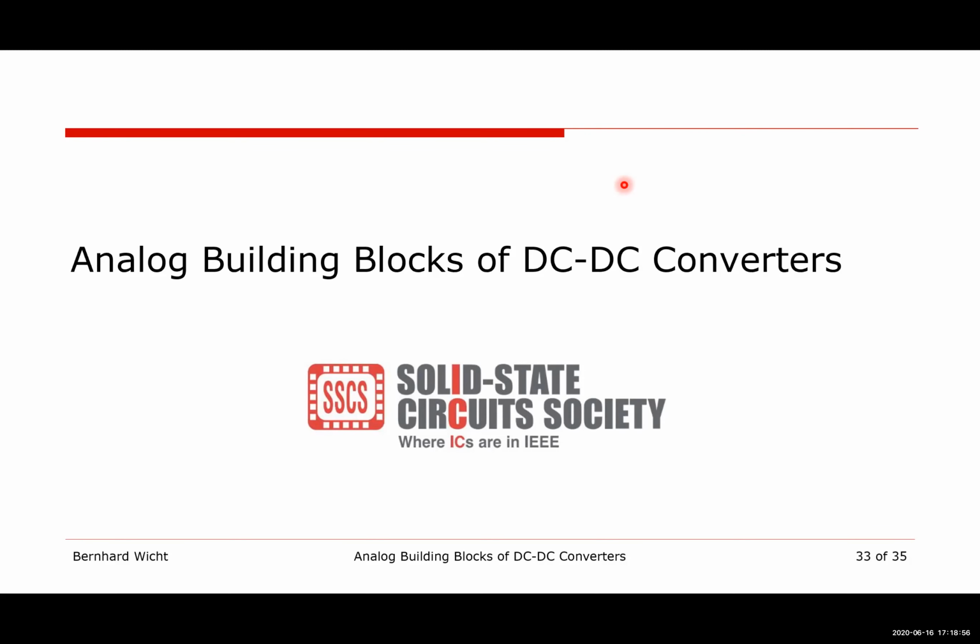For improved reliability, in case there is, for example, overcurrent or any other problem inside the chip, or any damage or discontinuity, there is a technique to put two regulators in parallel and combine them in some way without losing efficiency to achieve fault tolerance.